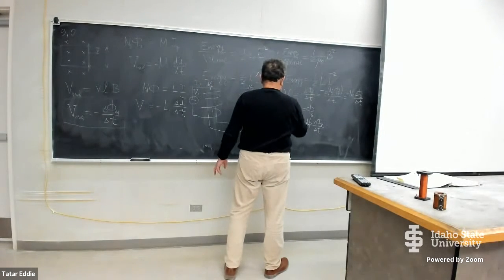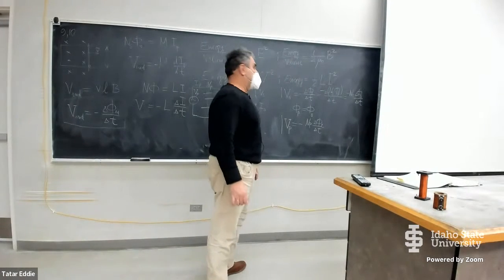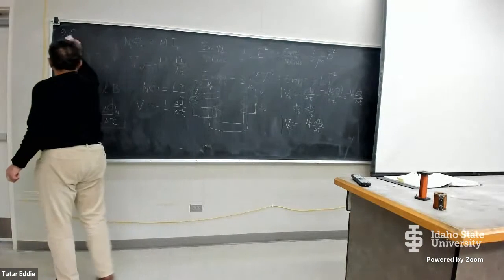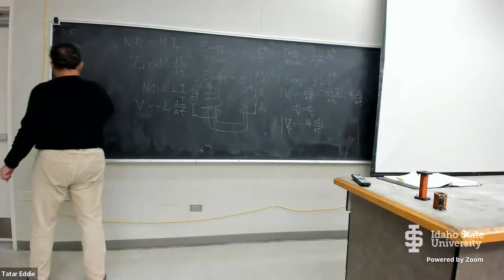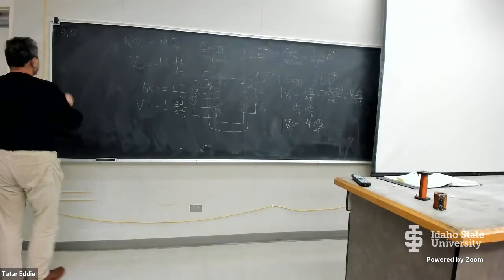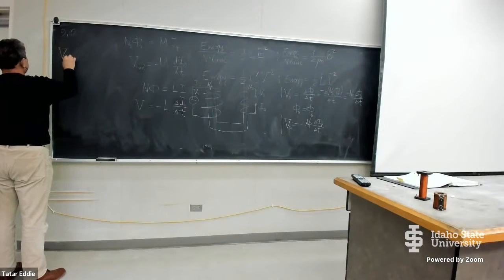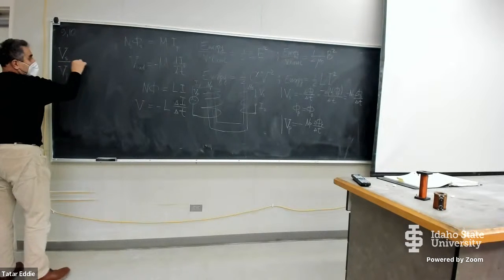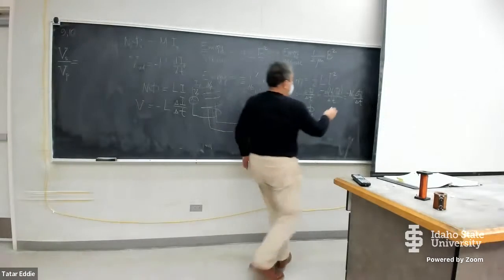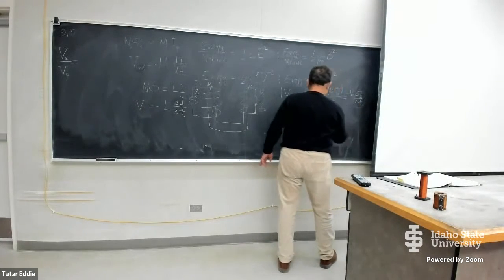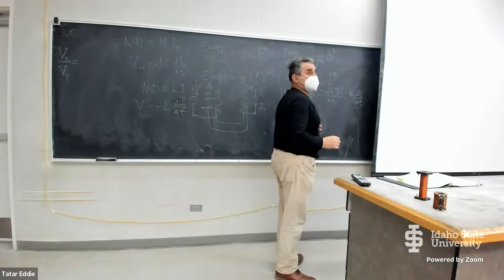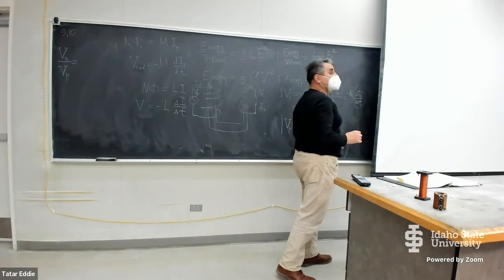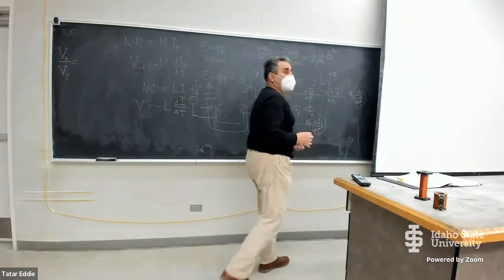So now take this and this equation and divide them, and you're going to get the following expression. When you do the division, you get the voltage in the secondary coil divided by the voltage in the primary. Well, this part and this part cancel out because the flux in the secondary and the flux in the primary are pretty much the same.